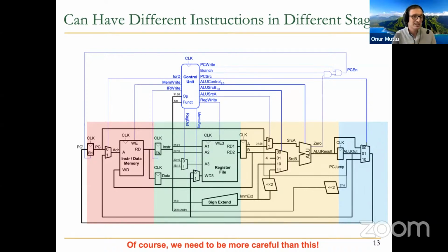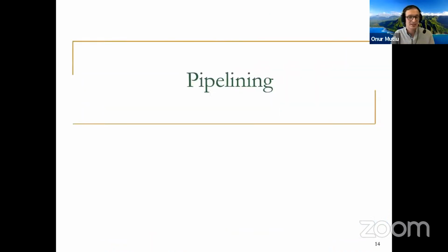That's why this picture, even though conceptually it's very nice, you should not take it as an implementation of a pipeline processor, because implementation does not go from multi-cycle to, okay, I designed the multi-cycle, now chop it up. No, it doesn't work that way. You really need to design the pipeline processor from scratch, if you will. In fact, the single cycle processor is an easier place to start and pipeline the processor. And we will see that. I will do that actually in this lecture.